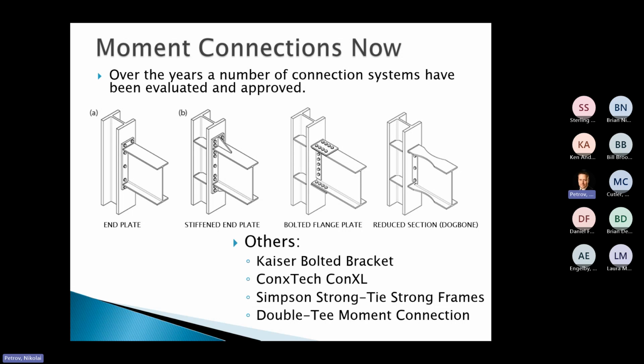These bolted end plate and flange plate connections, they have their place. Has anybody ever used those before? They are a pain. They're very rigid in terms of what geometry you can use them for, and what the maximum beam size is that you can use for a given moment frame. There's a lot of requirements on those systems, and sometimes it can make it really hard to get them to work. And you can sort of chase your tail.